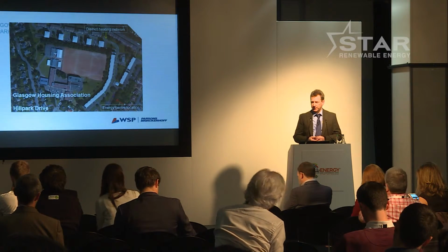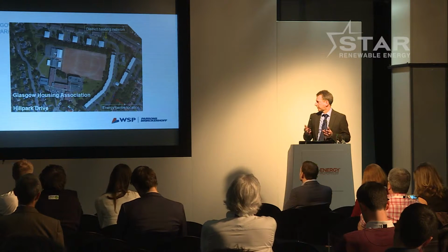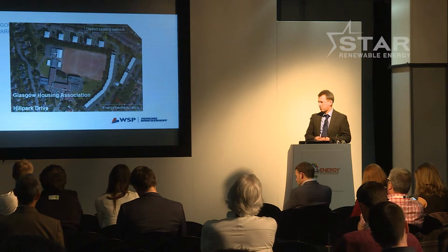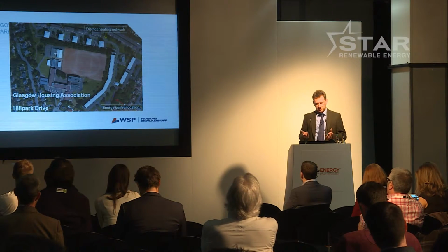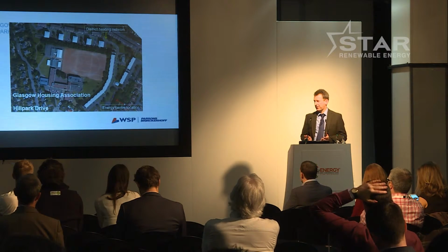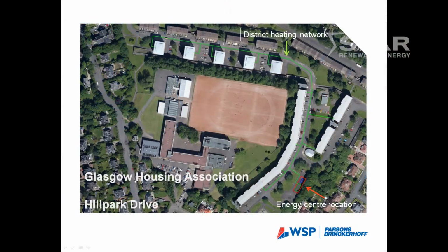They're all fitted with electric storage heating. It's an area of high social deprivation and fuel poverty. And a housing association doesn't want to put gas heating into these buildings, partly because of the high-rise issues and partly because of the issues with servicing and maintaining gas boilers in these properties. So we did a first feasibility study for them, looking at biomass versus heat pump options.